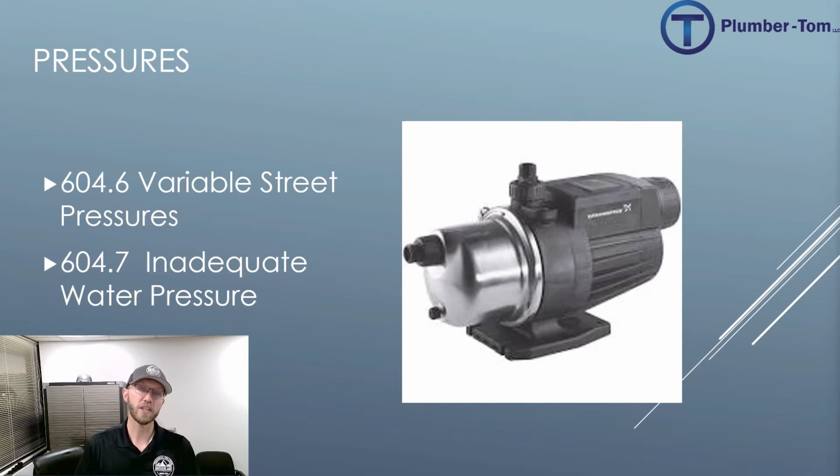In situations where that water delivery may be inadequate, 604.7 talks about providing more. It says wherever water pressure from the street main or other source of supply is insufficient to provide flow pressures at fixture outlets as required in the tables that we've looked at, the water pressure booster system conforming to 606.5 shall be installed.